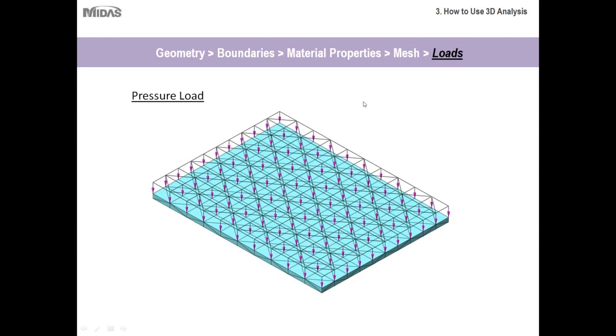And then the same with pressure loads. For those of you who are wondering how we're able to model 3D loads, you can model a distributed load such as this by selecting a certain face, and the program will automatically select the nodes and apply the forces along a distributed plane. And say you had a more complex loading type, with a higher level of loading in this area as opposed to this area, there are certain things you can do to manipulate the program to produce that asymmetrical loading.